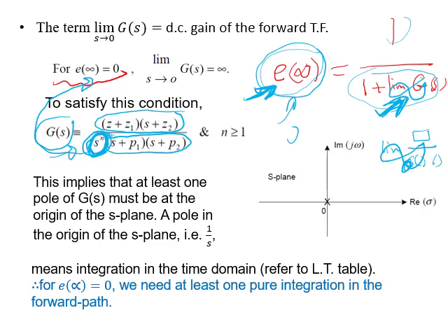So in any transfer function, if I have an integrator and we calculate the steady state error with step input, we are going to get the steady state error equal to 0. Even without calculation, you can decide that it's equal to 0. Notice that the integrator, 1 over S, means the value of S equal to 0, I mean, it is found at the origin.